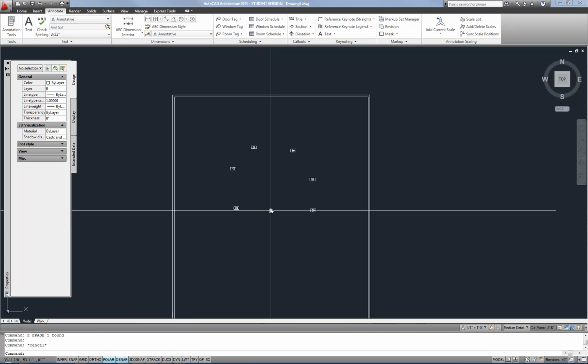Don't let the annotation scale issue confuse you. You don't have to use it. You can just make a block at a size you need. You don't have to check annotative. And then basically the block just sits there and has that modifiable attribute in order to represent the text inside it. An example of when annotation scale isn't necessary on a block is a title block.